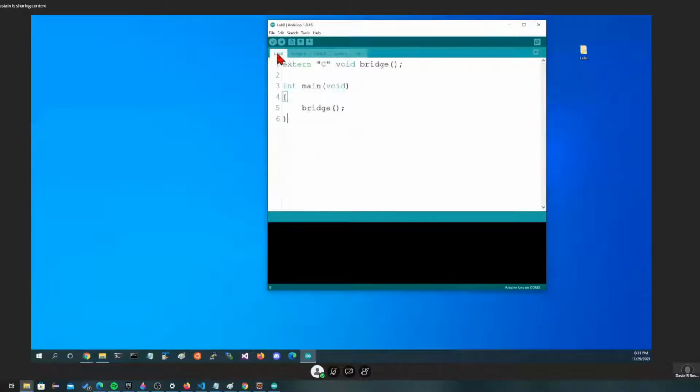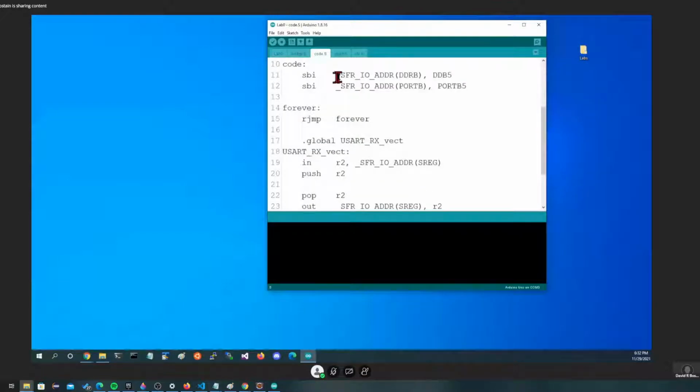Now, because we used main and called bridge directly, we did not call that initialization code that causes things to be misaligned for us. We fixed things by just calling bridge alone here. So we will cause the thing to be loaded. This method will be called every time reset occurs. It'll immediately jump into assembly. Assembly will immediately initialize the USART and then call the code we need. And if the code ever finishes, it'll just stay here hanging around forever. In our code we've written, that doesn't happen. We do a couple instructions and then we stay here forever instead.